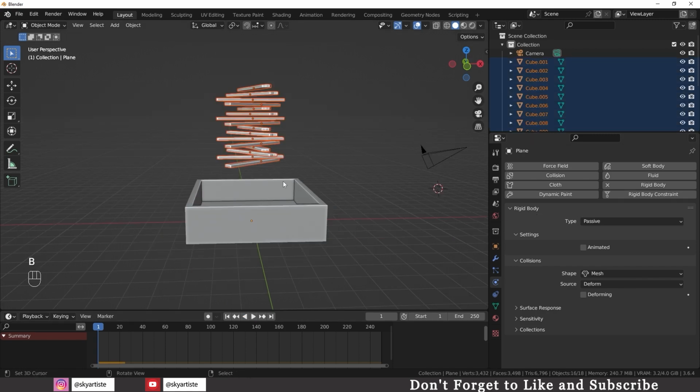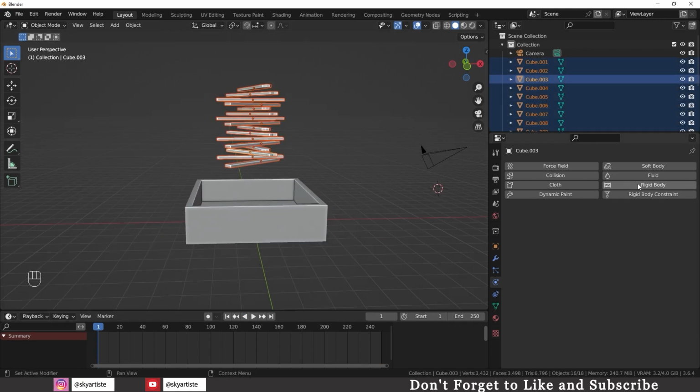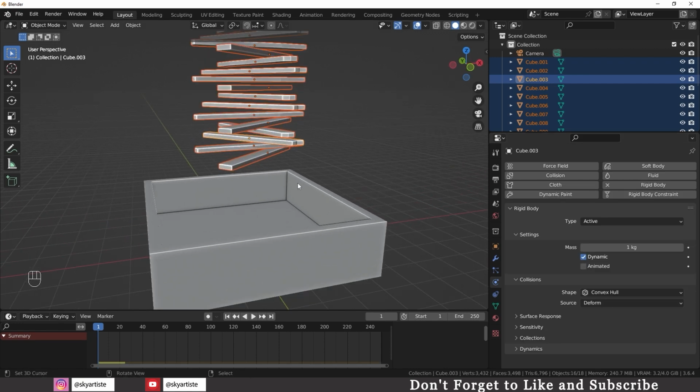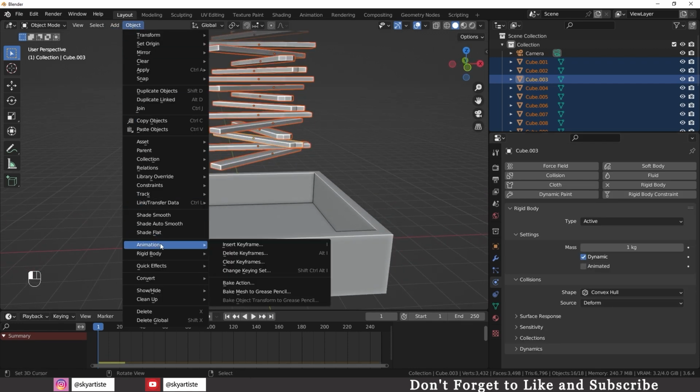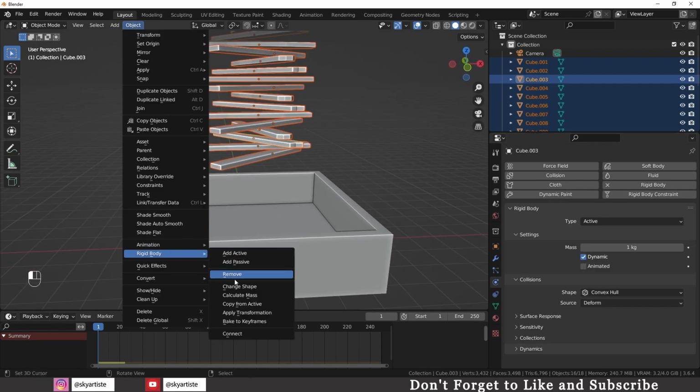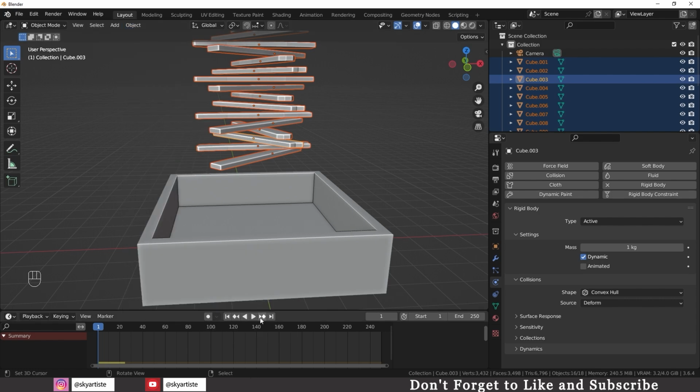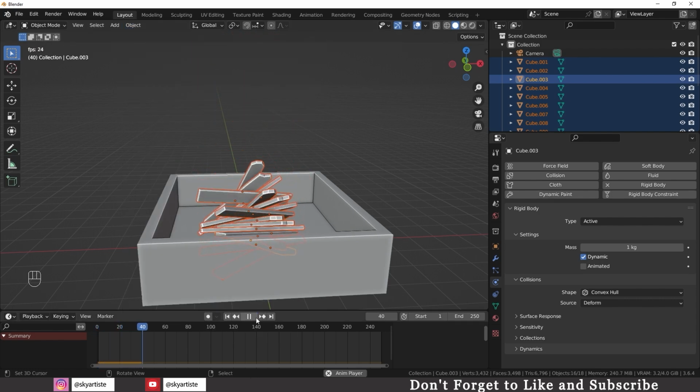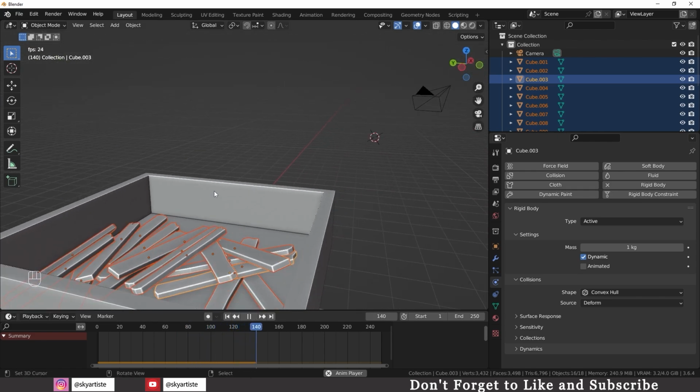Now we select all of our boards and determine one of them as the active object. We adjust the physics settings. We transfer the physical properties to other wooden models by going to the rigid body section from the object menu and clicking copy from active. Now we press play and we can see our wood stacked realistically.